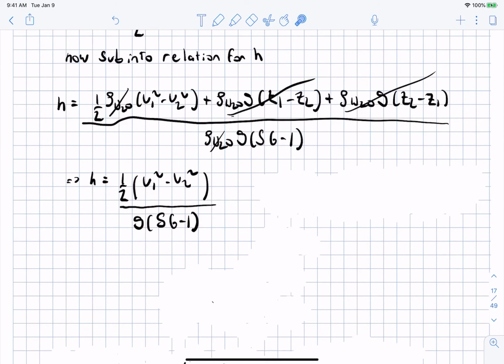Okay? And notice that it does not depend on the material, it does not depend on the elevation difference. That basically dropped out. The effect on the manometer and the Bernoulli equation basically canceled each other out, and that change of height, or the change of the elevation, does not matter to the manometer, which to me is kind of a nice result.